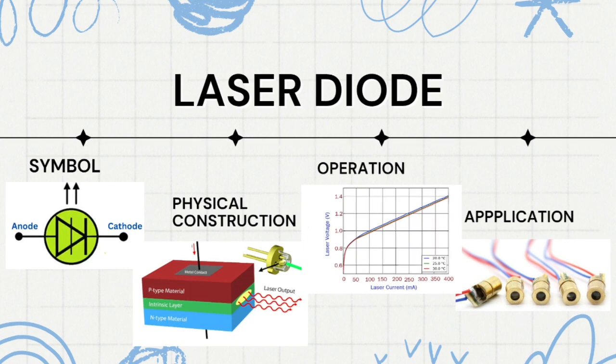Compared to an LED, a laser diode is a typical type of semiconductor device. It emits coherent light, or waves that are all at the same frequency and phase, using a PN junction. The laser diode uses a mechanism known as light amplification by stimulated emission of radiation, or simply laser. The current, in milliamperes, flowing through the laser diode grows quickly with a slight increase in voltage.